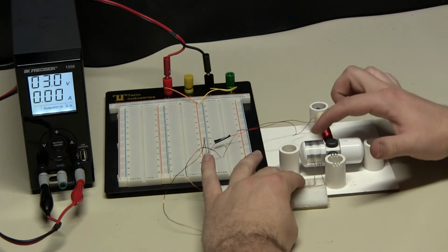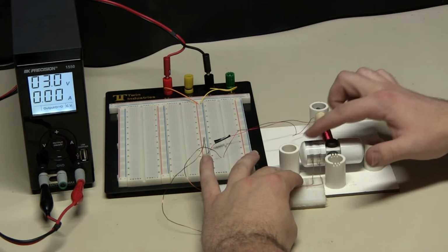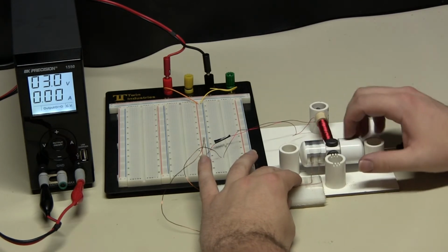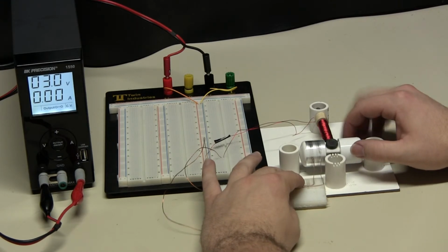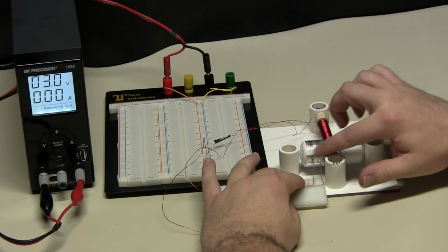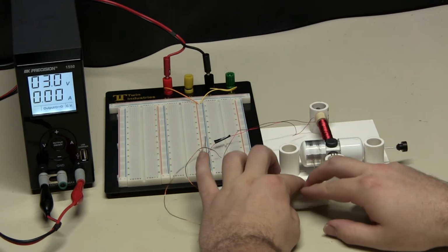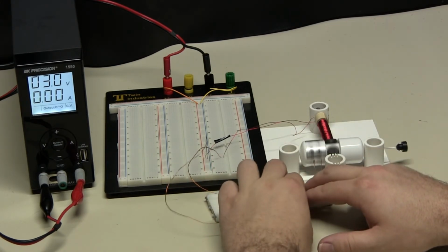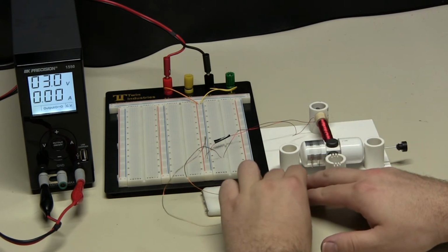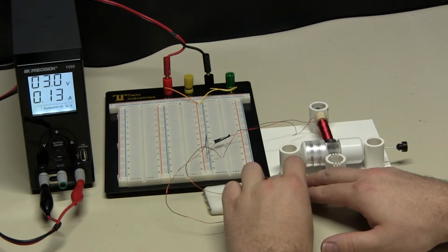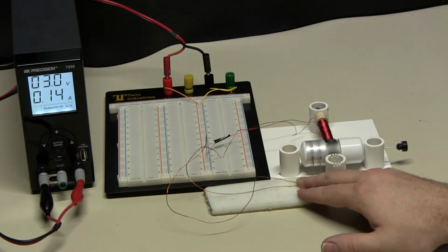These commutator brushes would be closed in when they contact these aluminum strips on the rotor, and then there's gaps in between where there is no metal, and in those places the circuit would be off and allow the motor to rotate. So these allow the circuit to complete. And you see when I touch it, the motor will start up. The downside to brushes, there's significant arcing, rubbing, and friction on these parts. So that's a downside to